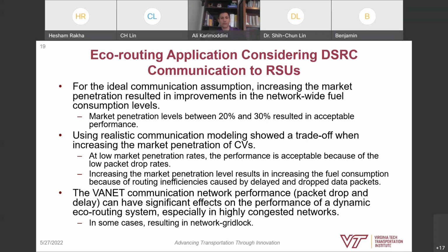Yeah, definitely. And I should also mention that we assumed that our roadside units would be at the traffic signals. So it was a min-max problem. We're trying to maximize the coverage of the network while minimizing the number of roadside units that we need to provide that coverage, subject to roadside units only being at traffic signals where power is available. So we also had holes in the network where we couldn't capture the information, because we didn't have any traffic signals where the roadside units would cover that area.